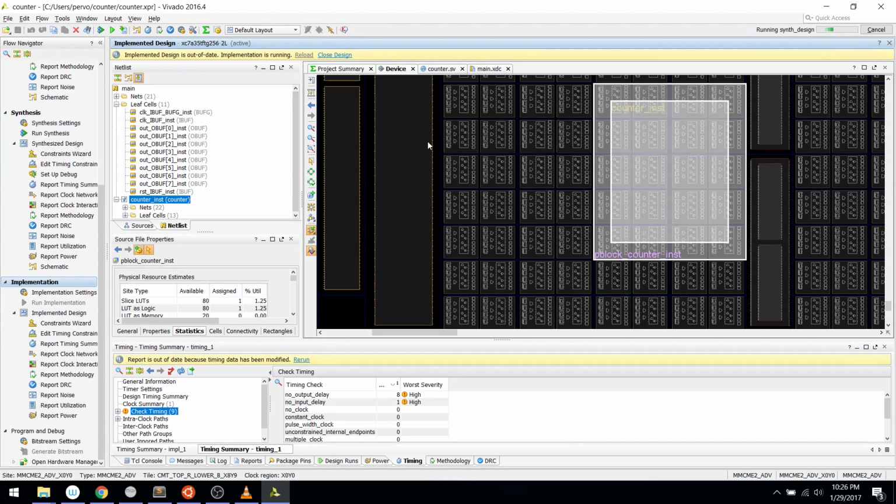There's something called relatively placed macros in Vivado, which is an older feature, or a newer feature called XDC macros, which are basically a way of specifying relative placement constraints between submodule blocks, for example, in a way where you can reposition them without destroying the constraint, but still having this notion that, hey, I want to place this block near a block RAM, or I want the ALU to be right next to the bank of registers. So you can do some constraints and then have the placement and routing system figure out the nitty-gritty details of exactly how to lay things out within those constraints.